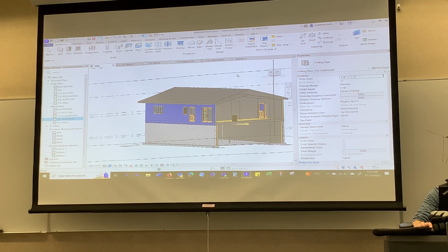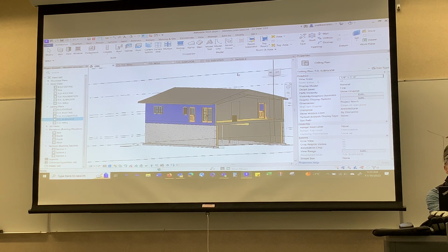And that's fine. Okay, stairs, the first thing, this is sort of designed for an online class too, and I used to get people to look at the code and find out what the mins and max are for residential rise and treads. And then you also have to worry about headroom. Okay, so remember when you do the basement, that beam is in 2 pieces? There's a reason for that, because you're banging your head going down the stairs. And I forget what it is, it's something like 78 inches or something like that. It's pretty high.